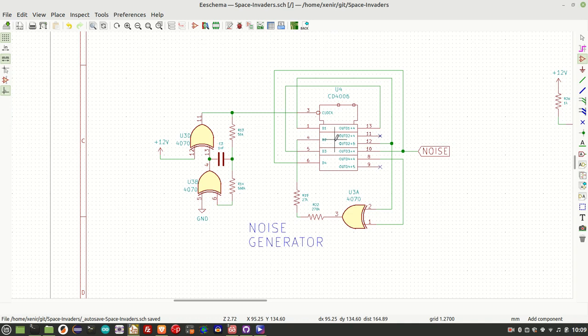There's a great article on EE Times, which I'll provide a link to, that explains kind of how this all works. And the trick is choosing which taps of the output to feed back into the input to produce a maximal length pseudo-random sequence of bits output. Now the frequency of the pulses is set by this clock here, which comes from this XOR gate oscillator right here.